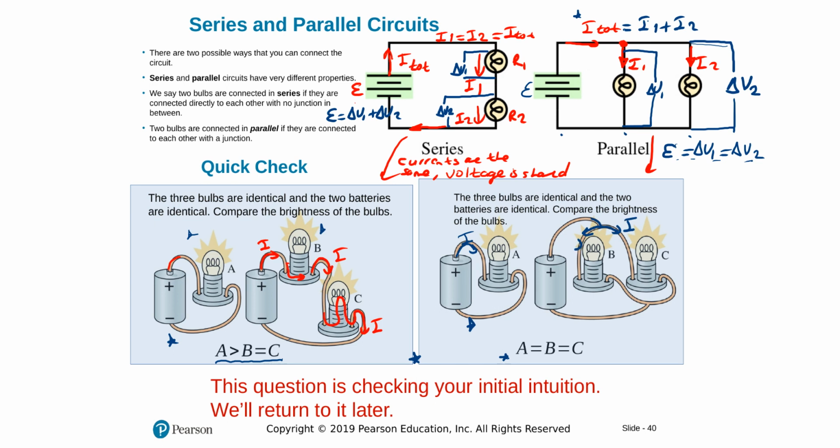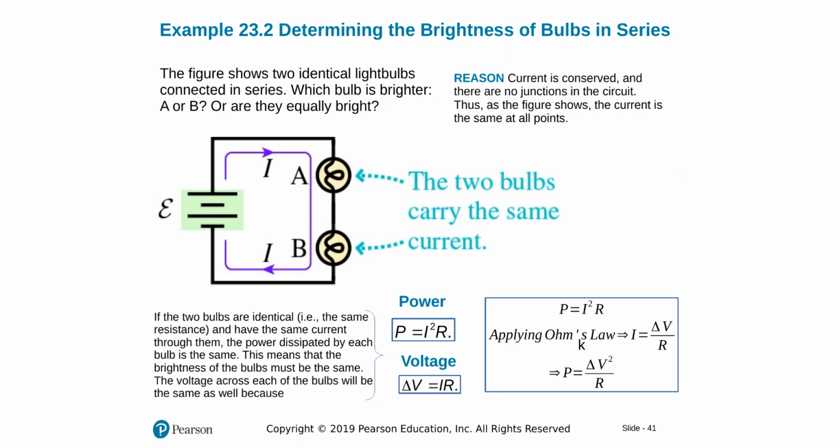But what will happen is, if I have two parallel bulbs in the same power supply, they will draw twice the current from the power supply and they will share it equally, so they will have equal current with the first lone bulb here. Brightness depends on the power, and power here is described simply by I squared R. So when I know the current passing through a resistance and the resistance, I can calculate power, high brightness, or a better brightness.